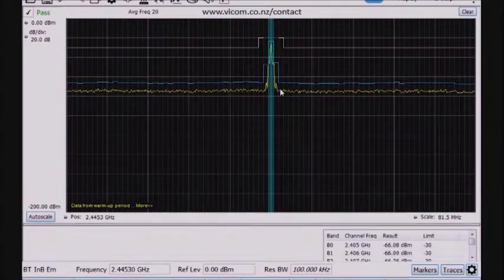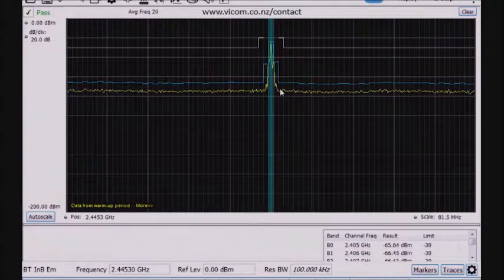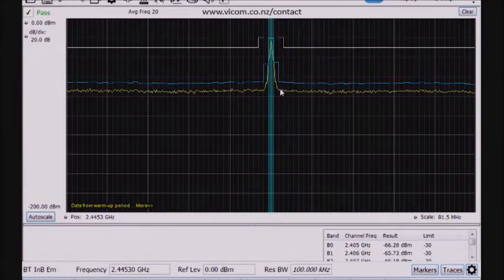So that's an important test to make sure that you're not interfering with other users of the ISM band with your device. And there the averaging didn't work, so it hopped around and searched for it again. By the way, this averaging problem goes away if I use the DPX display, the real-time display that's available here, but I don't have that available within this in-band emissions test. It's just the basic spectrum display. So that's the first test that I would do for EMI pre-compliance.